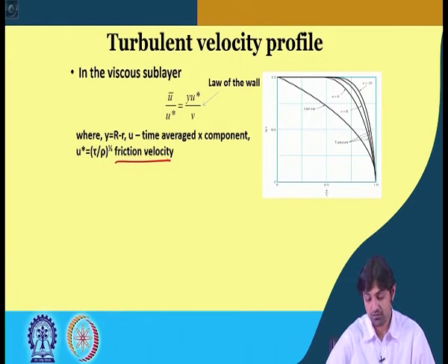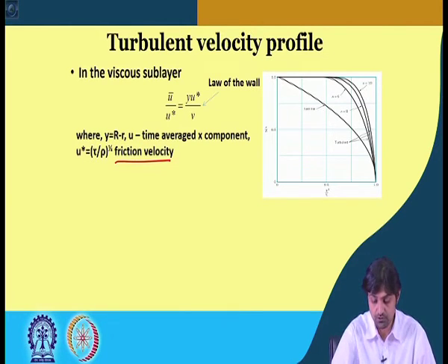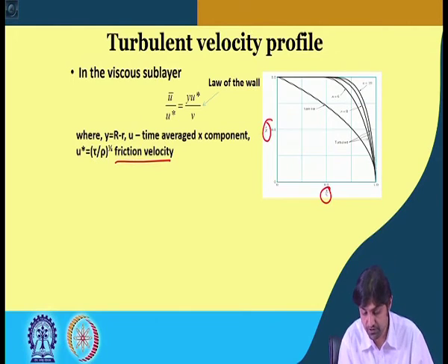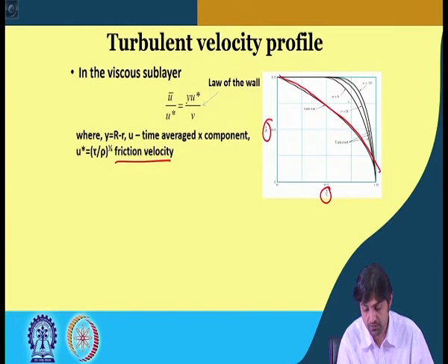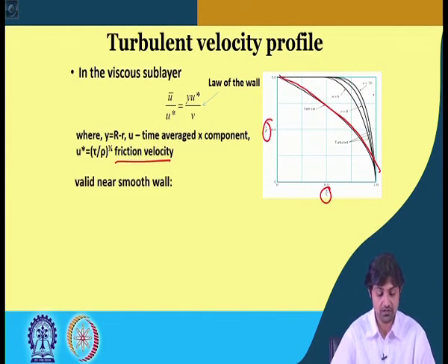There is a figure here using u bar by center line velocity and r by R, where the laminar flow curve is given, and there are curves for n is equal to 8 and n is equal to 6. What that n is, we will come to.